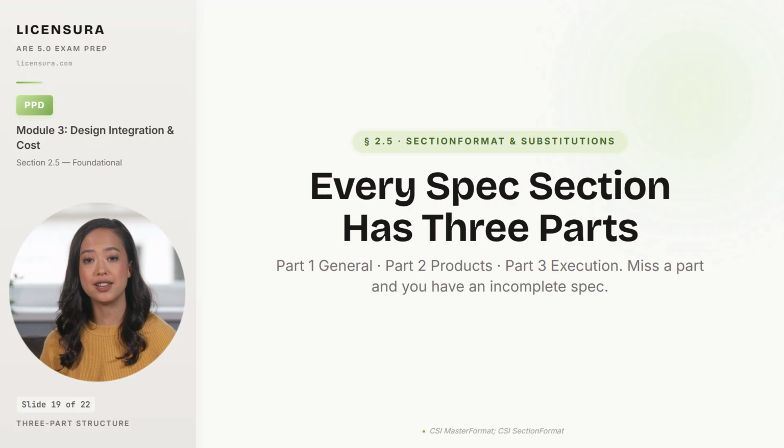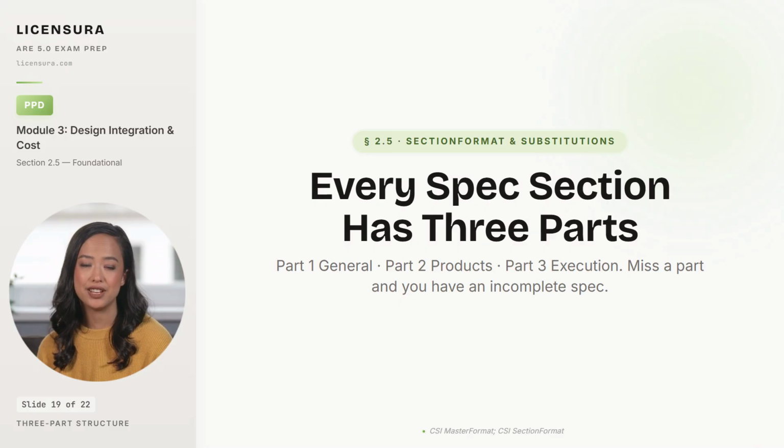Part 2 is products, the materials, manufactured products, and equipment that get installed, including acceptable manufacturers and any fabrication or mix requirements. Part 3 is execution, how the products are installed or applied, covering preparation, installation methods, field quality control, and cleaning. Every spec section has the same 3 parts in the same order, and the exam tests whether you can identify what goes in each.